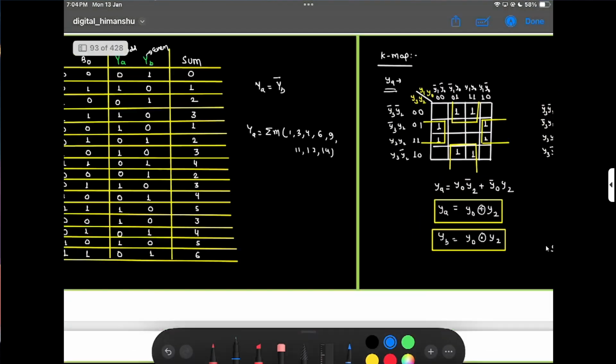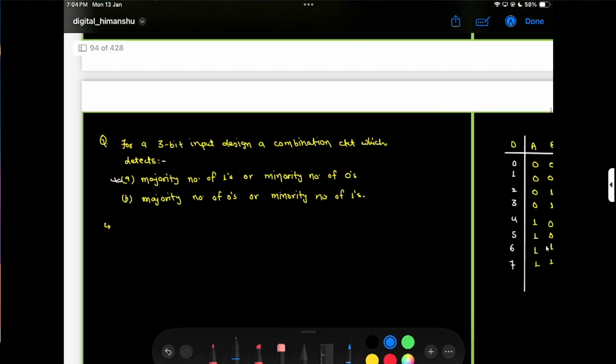Okay, leave it. Everything in this question is the same. Whenever a combinational circuit question comes, just read the requirement and design the black box accordingly. In the black box, wherever the output is 1, go through the K-map, using the circuit inputs, and that's the way you can make the circuit by designing it with logic gates.